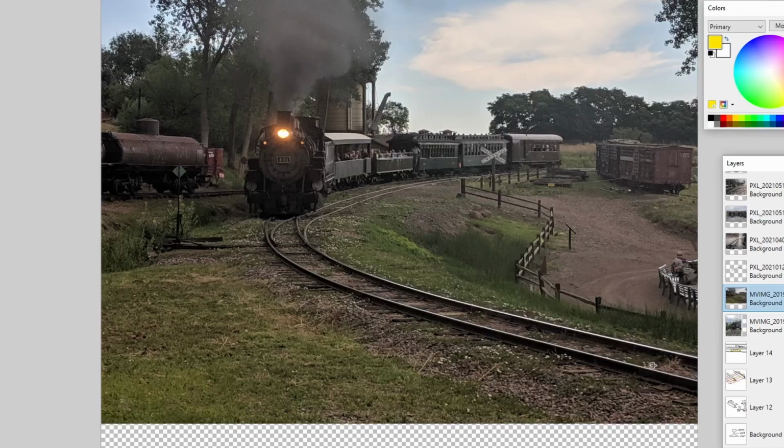But basically what happened was, without having sufficient ballast, we basically just had dirt or river rock there. The track was slowly pushed over each time we ran over it until there was one critical spot where it basically just turned really hard like that, and you felt it as you ran over it. I mean, the locomotive turned on a dime, and that's not a good feeling. We were running at night, so it was hard to see, but we knew it felt wrong, and something was wrong, so we called the boss to come inspect it and see what was going on.